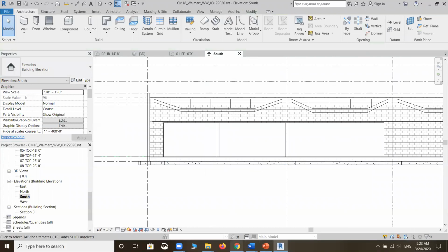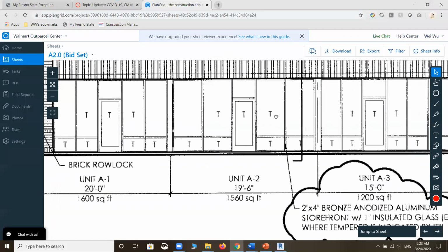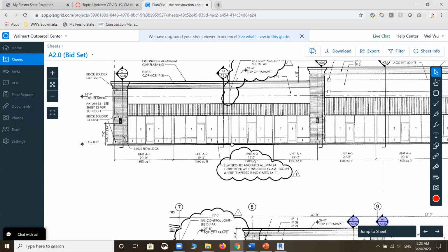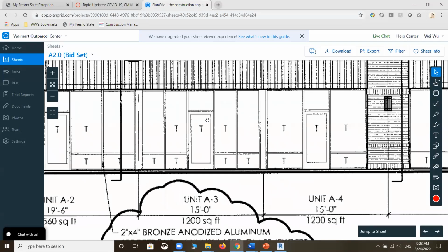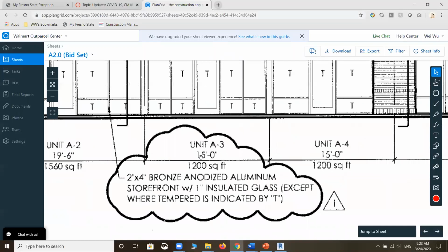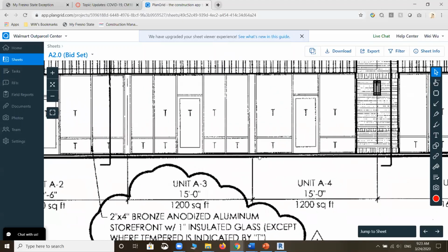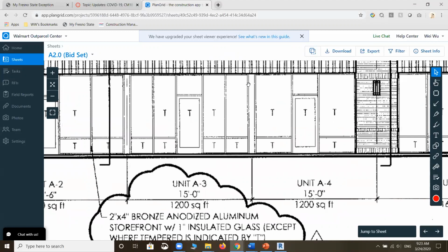So now, how about the other side? Same thing here. You see that grid line number 2 is here, but the small panel that separates those 2 subsections of a curtain wall is here. That is 15 feet away from it. Again, I cannot directly determine the location of the edge of that panel, which is those 2 cutting grids, but I can always place that pretended cutting grid first, then put 4 inches on this side, 4 inches on the other side, then I delete the one which I don't need, right?